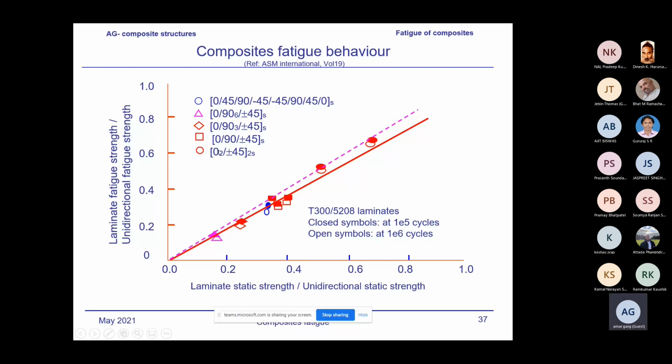I'm not sure. They won't have been able to apply R equal to -1 for this thickness. It might have been for positive tension. It doesn't say; I'll look into the real reference. It should be tension, because you can't apply compression to such a thin laminate. You won't be able to test it in tension-compression. So it must be a tension-tension cycle.